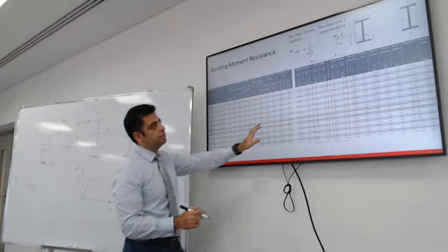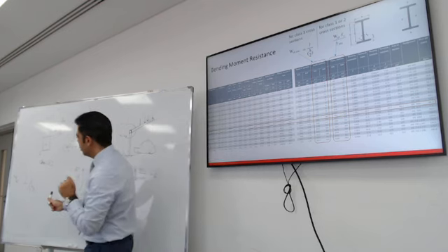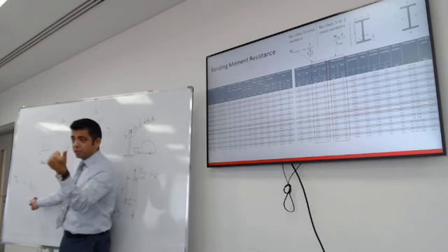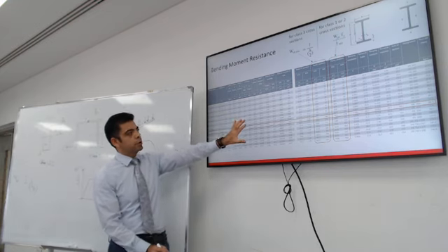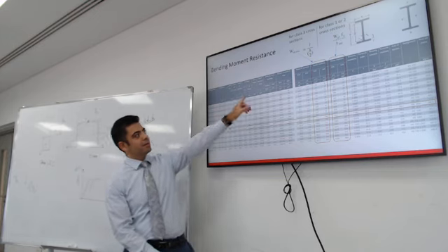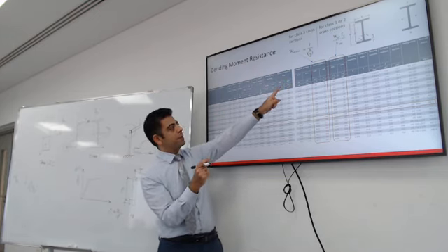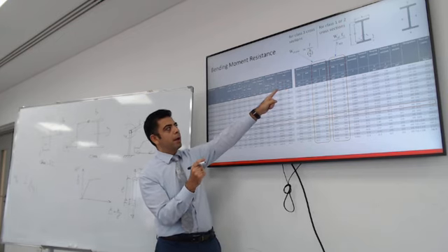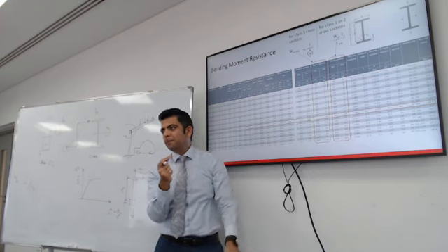This table will do this math for us, since it gives us h and it gives us the moment of inertia. So what is the moment of inertia of this section? Moment of inertia is the second moment of area. It has two values, one about y-y and one about z-z, the one with respect to the y-axis and the one with respect to the z-axis.